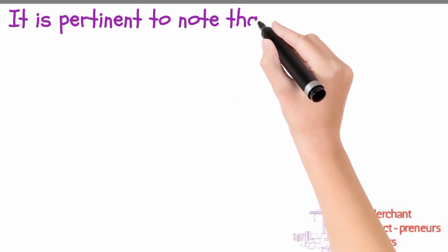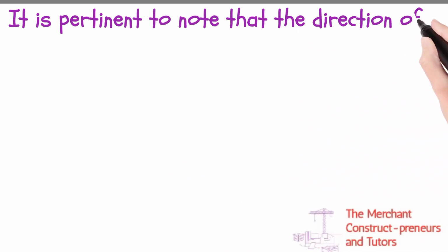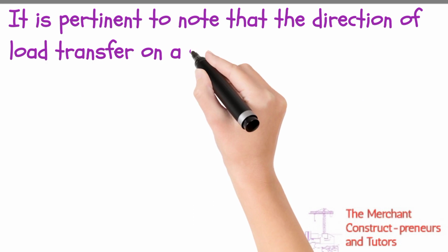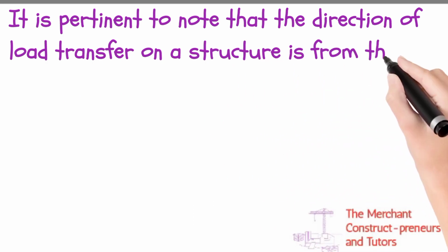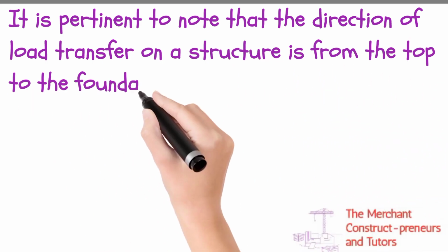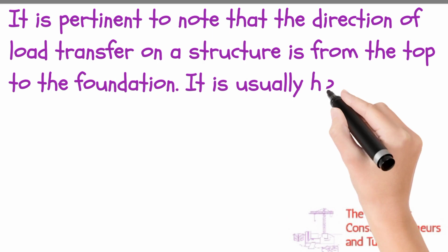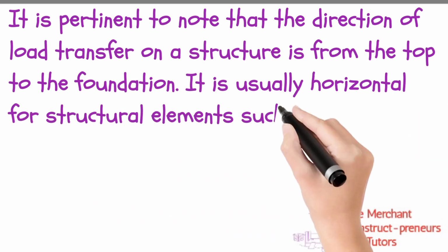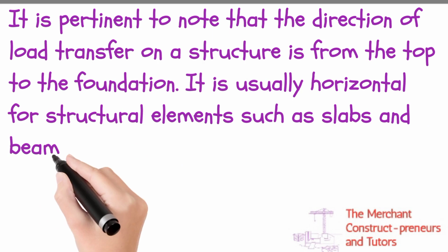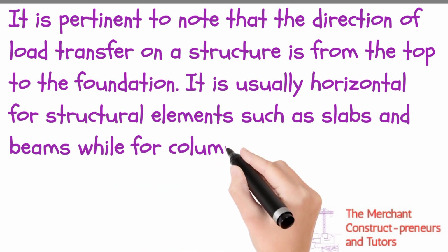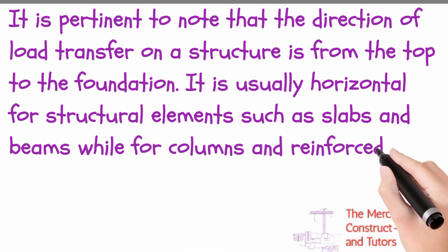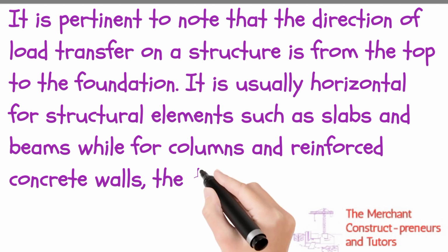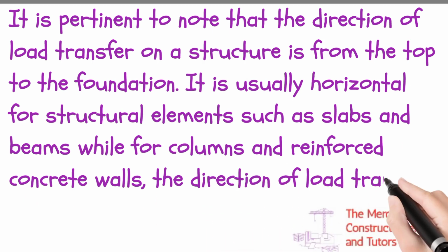I hope you understand that part. As we go further, you will understand it better and more clearly. Good. So for the roof beam level, we have started breaking this down, starting from the top, the roof. From the roof beam level, the roof beam collects load from the roof structure and the self weight of the roof beam, and then it transfers it to the column.